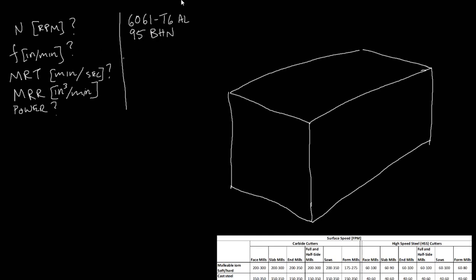We're going to use maybe a 1-inch cutter, so a pretty big cutter. So that'll be, let's call this an HSS end mill. So that HSS is high-speed steel, and it's going to have 4 flutes. Okay. So the cut that we want to make is 0.75.